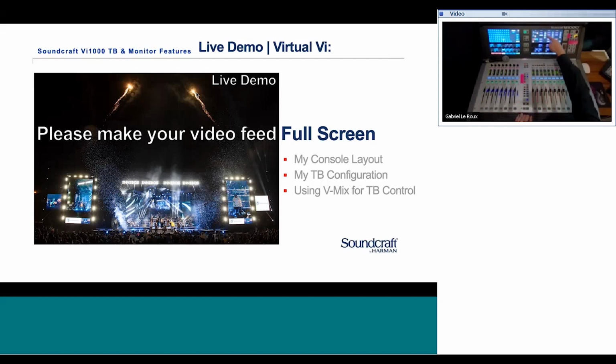I have solo in, solo out in, and then also my Talkback Return, which in this case is going to be my front of house engineer. And I have selected the center to be part of what's coming into monitor A. Then all my Talkback channels are brought onto my console and I've isolated them. You can see they're all purple. The ones I'm using at the moment are these two. It might be a little bit small for you to read on this top view. The first one is my Talkback Mic.